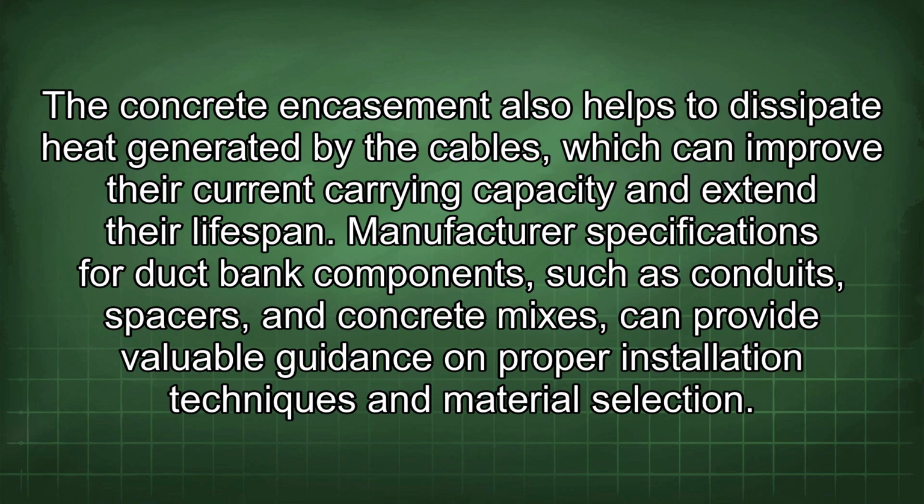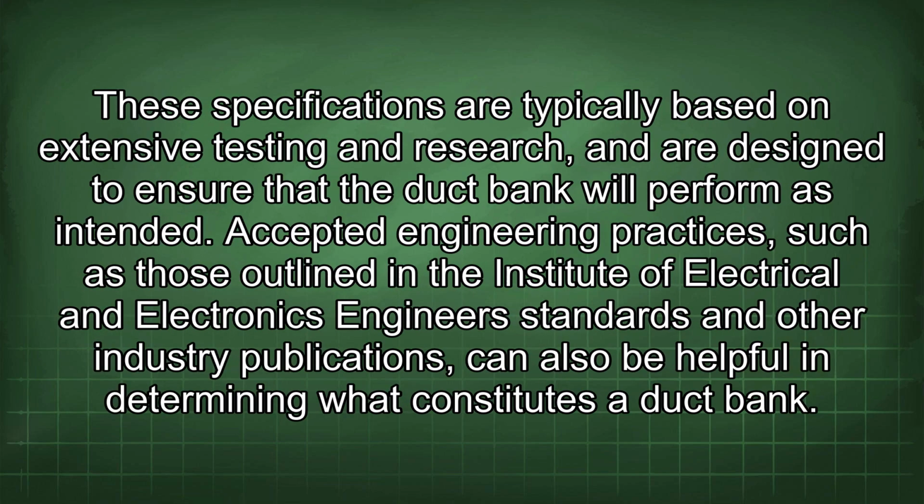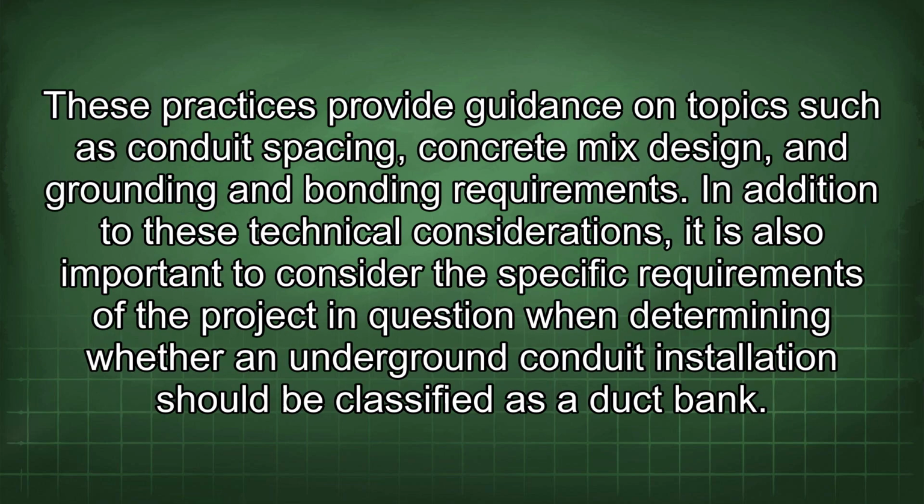Manufacturer specifications for duct bank components, such as conduits, spacers, and concrete mixes, can provide valuable guidance on proper installation techniques and material selection. These specifications are typically based on extensive testing and research, and are designed to ensure that the duct bank will perform as intended. Accepted engineering practices, such as those outlined in the Institute of Electrical and Electronics Engineers standards and other industry publications, can also be helpful in determining what constitutes a duct bank. These practices provide guidance on topics such as conduit spacing, concrete mix design, and grounding and bonding requirements.